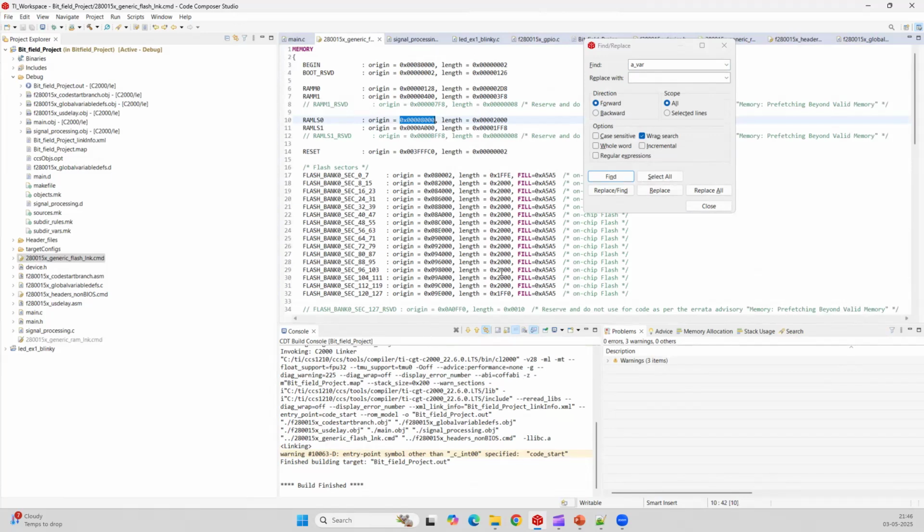The reason behind this is that during the startup, after the code starts, it will call some boot.asm file. In the boot.asm file, this .cinit, for all the examples provided by TI, or when you use the same type of project setup environment, if you check the boot.asm file, it will copy the global initialized variables to RAM after the startup.